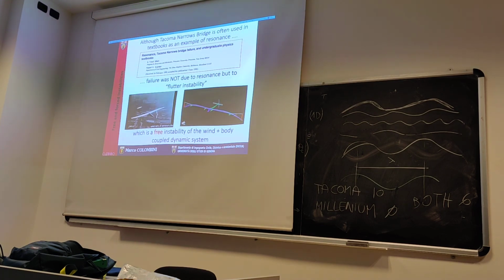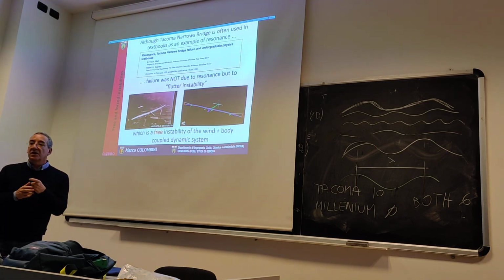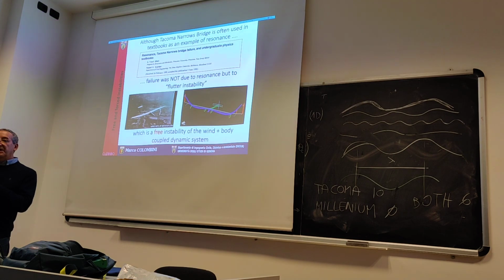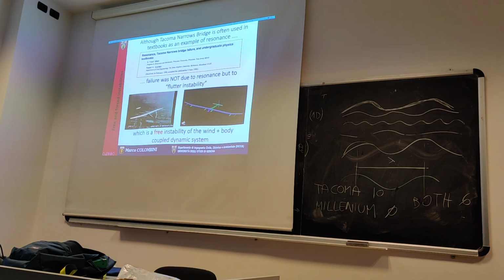So the distinction between point bars and free bars, the alternate bars I showed you are free bars, is built upon this concept of resonance. If you study the solution in meanders, then you will have a forced solution, and sometimes, if we have time, I will talk to you about some resonant value of the width adaptation.